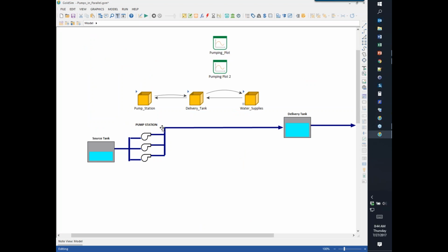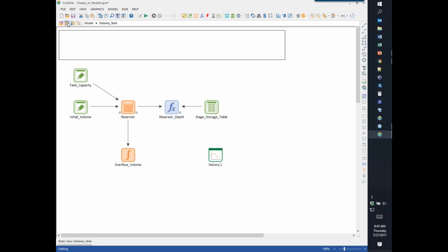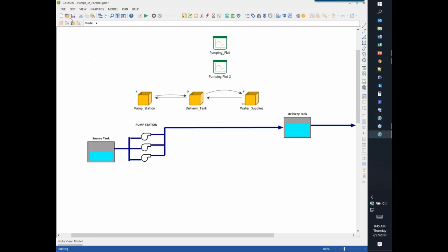Okay, so then the same thing, we just have a tank up here, very similar to what we had before. This is very simple, but essentially all we're doing is saying we have some water depth that contributes to the total dynamic head on the pump, and then we're going to monitor that through time, and this is the main control point that's telling us which pumps to turn on, and the head losses through the pipe, of course. But now when we run this model,